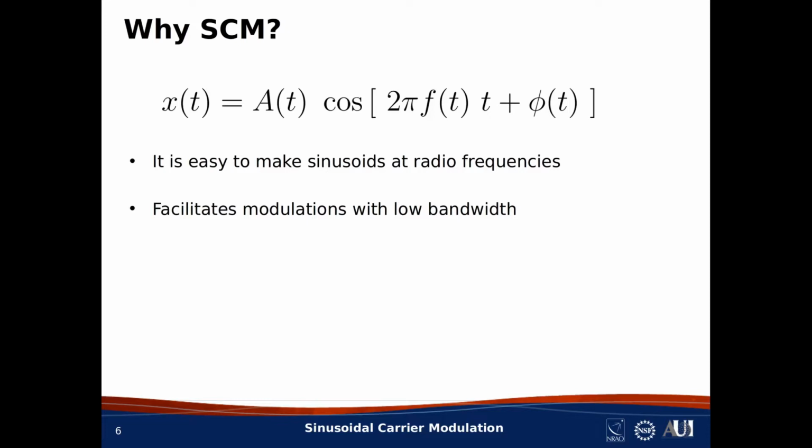There are many waveforms that you could imagine using to send information in lieu of sinusoids. For example, you might consider doing this with square waves or sawtooth waves. There are infinite possibilities. But there are two things about sinusoids that make SCM the most popular method. First, it's really easy to make nice, clean sinusoids at radio frequencies. In contrast, virtually any other periodic waveform is more difficult to generate. Second, SCM facilitates modulations with very low bandwidth.